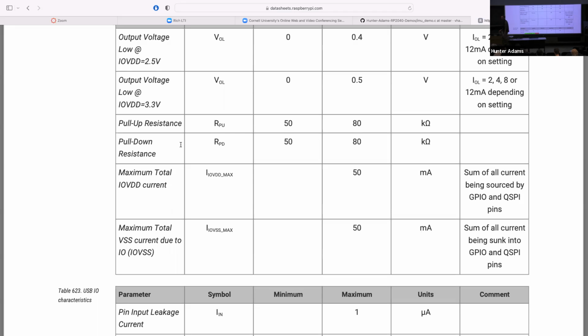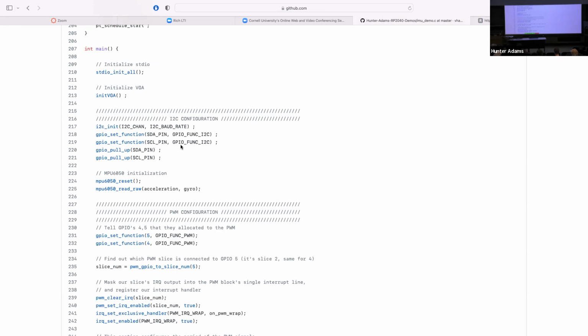So if you're having problems associated with noise, one of the ways that you might mitigate that problem, there are a few strategies, but one is stop using the pull-up resistors, which is as simple as commenting out these 2 lines, and instead breadboard an external pull-up resistor on each of the I2C lines that's 4 to 5K. And then I expect that you'll see much sharper transitions on your I2C lines. And by the way, scope the I2C lines, always. Always scope the I2C lines just to see what's going on.